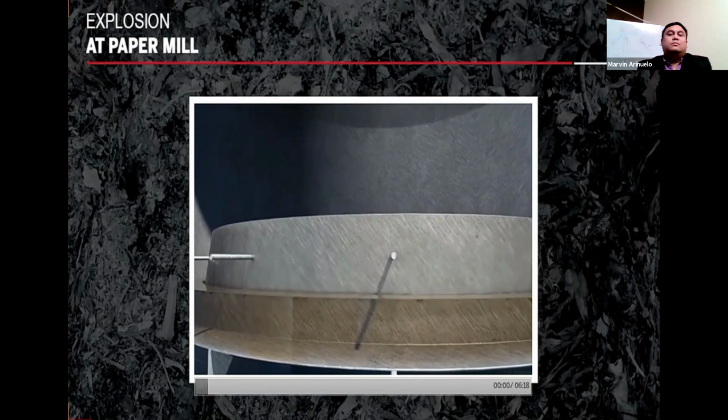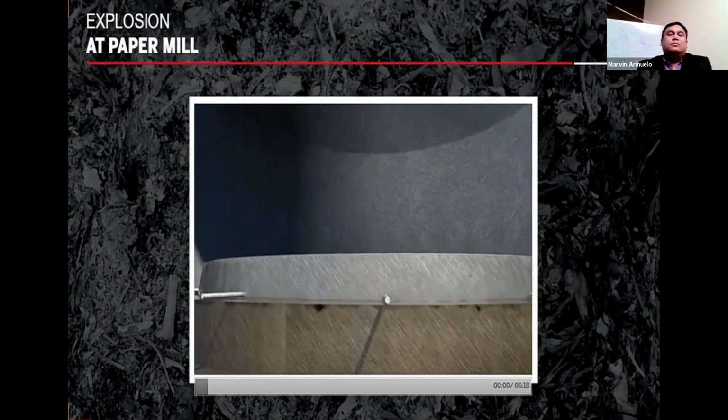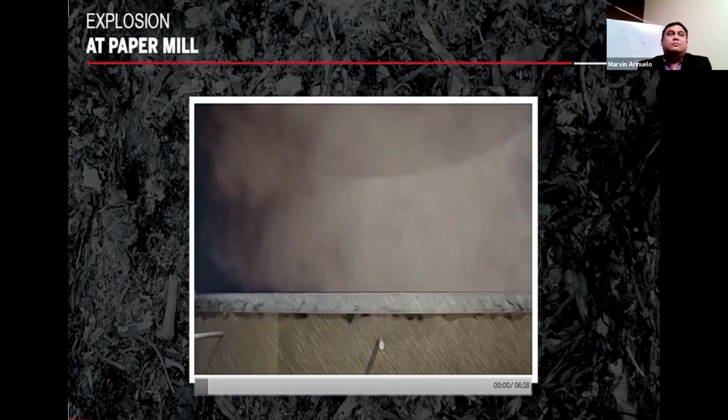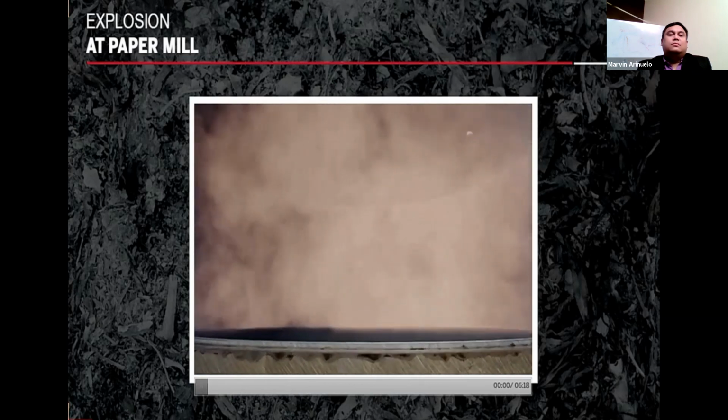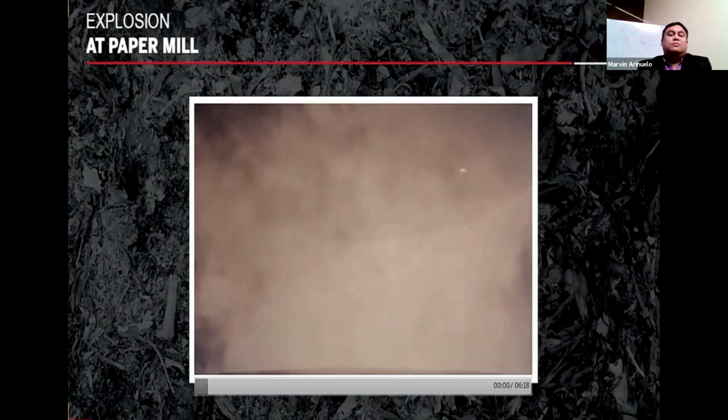In addition, there are normally vapors inside the foul condensate tank in the space above the liquid. Although those vapors can become flammable, they are supposed to be kept at a concentration that is too rich to burn. But due to the non-routine conditions experienced during the annual shutdown, the contents of the tank likely cooled, creating low pressure within the tank.